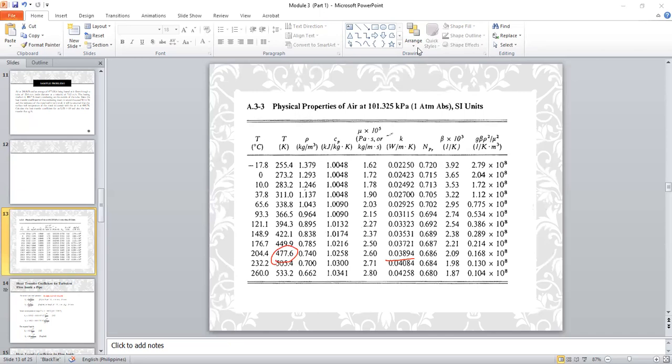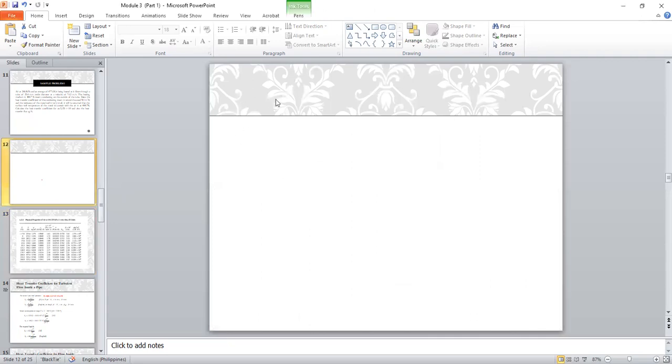So now we have already HL. We can go to the heat flux. So for letter A, class, that's already your answer, the heat transfer coefficient, and that's 63.2 watt per square meter Kelvin. For letter B, it's actually Q over A. So in that case, you need a formula, the primary equation that we're using for convective heat transfer.